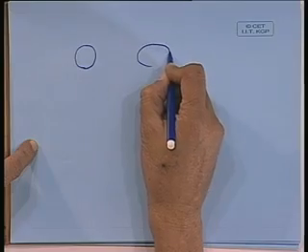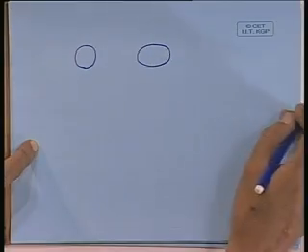The stress concentration, I wanted to only cover this much, and all these experiments can be conducted because there are various shapes which are available now to be used in ships, like the circular hole is one. Then you may go for some sort of an elliptical hole also, like in lightning holes we use.